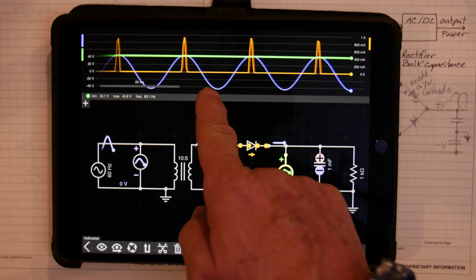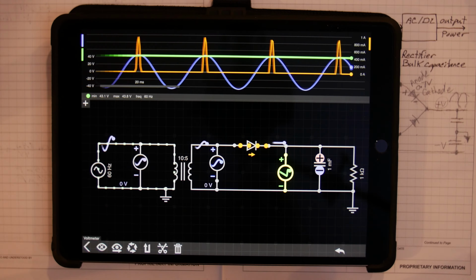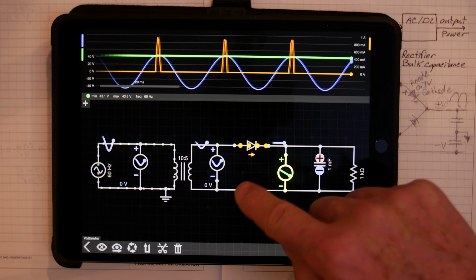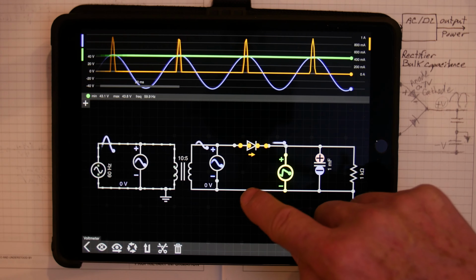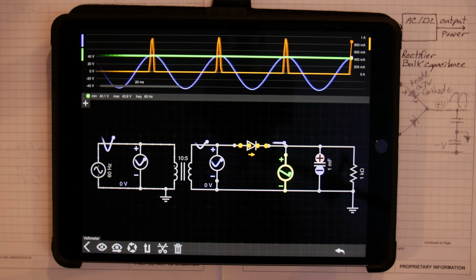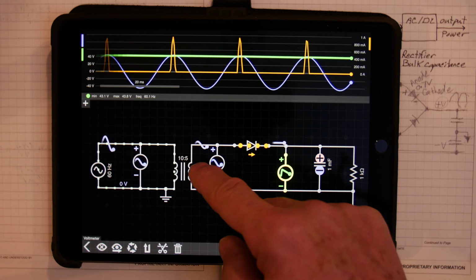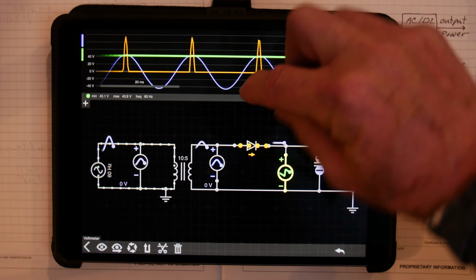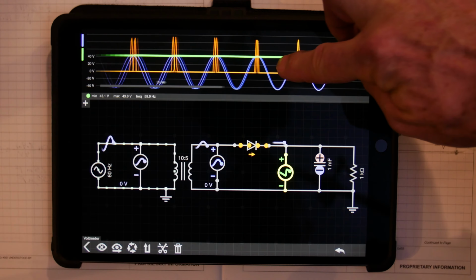But at every half cycle, we're getting a negative pulse. It'd be great to get a diode to direct that negative pulse up to here. So when you think about it, this transformer, during one moment, let's spread this out a little bit.